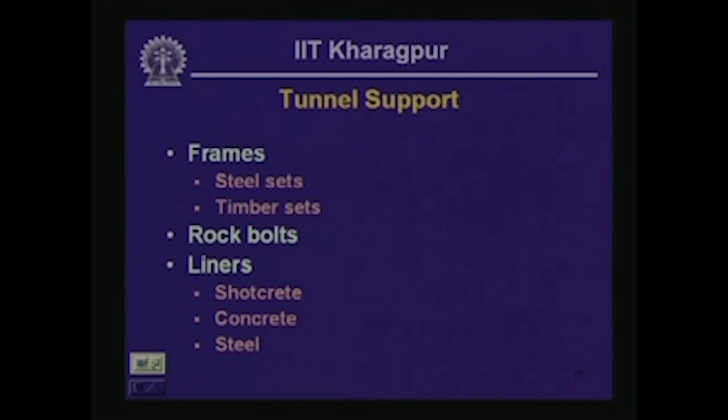They include shotcrete, concrete or steel liners, which are all in close contact along the entire surface of the tunnel wall with the surrounding rock. Because of the contact, these measures provide stability to the possible unstable rock mass near the wall and the roof of the tunnel.